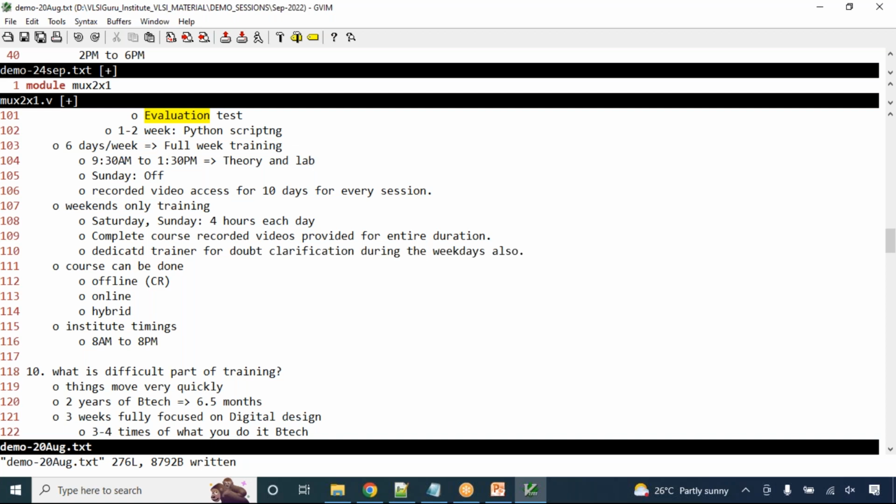See, in RTL course, RTL design and integration mostly refers to ASIC flow. If you see, chips can be implemented in 2 ways. One is using ASIC, application specific integrated circuit. One is through FPGA. For FPGA, we already have boards like Xilinx or Ultra, different boards are there, right? So whatever RTL code we do, we synthesize it and we put it onto the board. And while doing that, we have to be concerned about floor plan and the timing closure, everything.